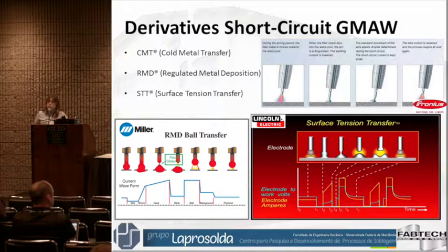When the drop approaches the melted pool, the power source controls the increase of the current to make the drop grow more smoothly, and when the drop touches the melted pool, it controls the decrease to make the transfer smoother also, increasing the influence of surface tension and decreasing a little the influence of the electromagnetic force.